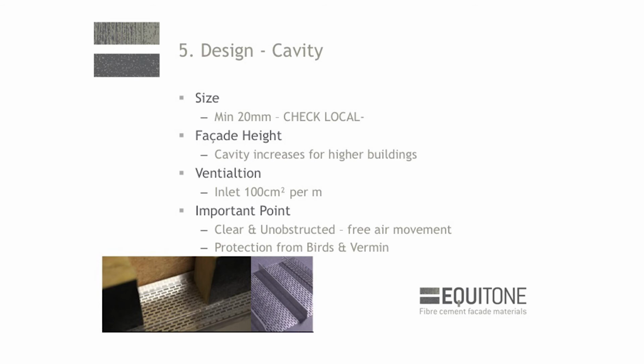However, protecting from birds and vermin, that's fine. But you can see everything is grilled. You're going to be asking about, and don't forget we have a 10mm joint. So anything bigger than a 10mm gap, you use protection.